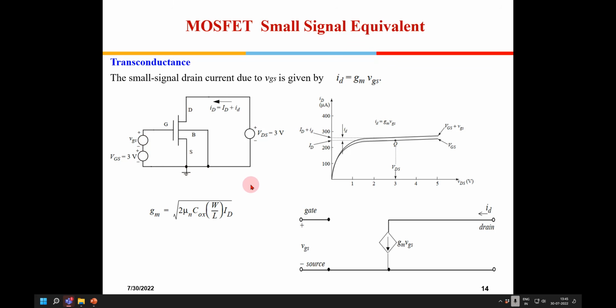There's no issue. Okay. Can it be said that when we are talking about small signal equivalent, we are considering a noise component in it, and when we are talking of large signal equivalent, there is no noise, just maybe a DC offset? Not noise. The actual signal is small signal. See these DC currents: we are giving these DC signals just to ensure that this MOSFET is in the required region.